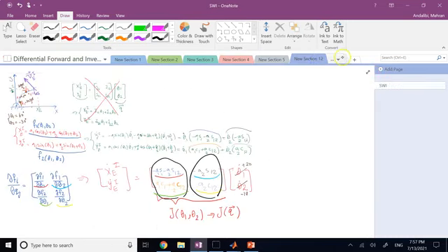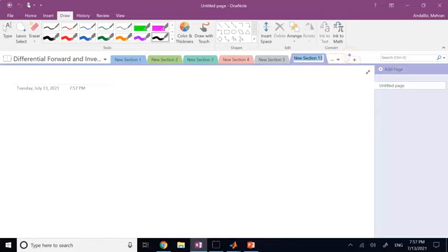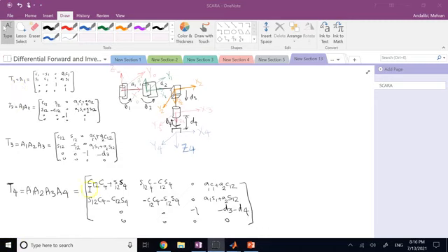Now, if I want to show you another example of this, we can look at, for example, a Scara. So for a Scara, we had the DH table and everything, and for that we can get the T matrices. Now let me show you the T matrices for it. So the T matrices for a Scara are these guys that we have calculated, or I have calculated. That was the robot, the frames, frame 0 all the way to frame 4. The specs for it, it had theta 1, theta 2, d3, and theta 4. There is also this constant d4 here, the offset.